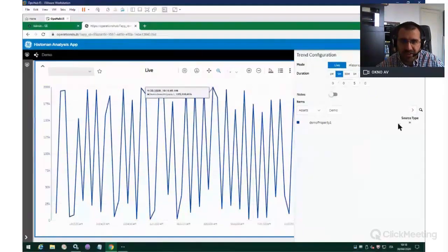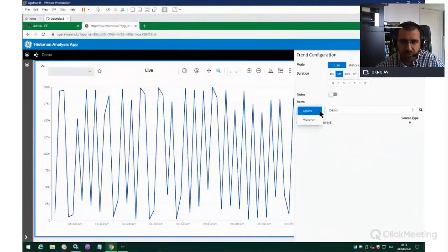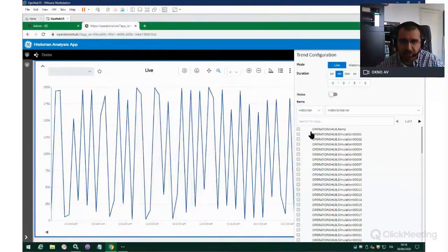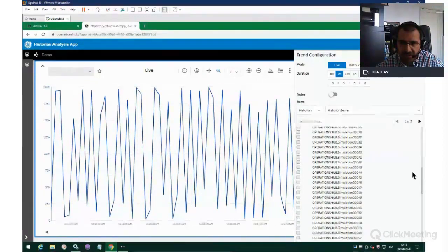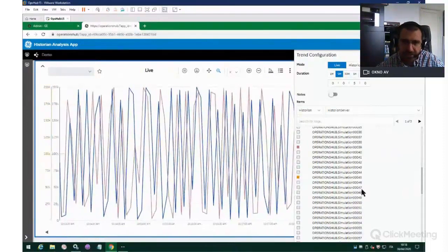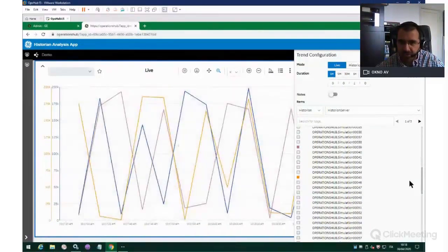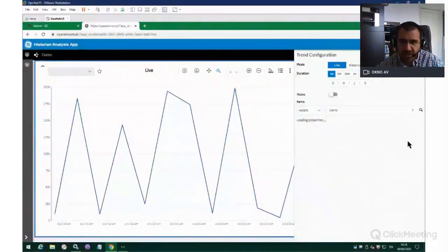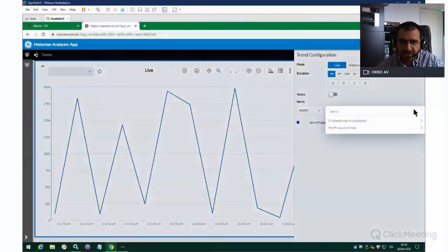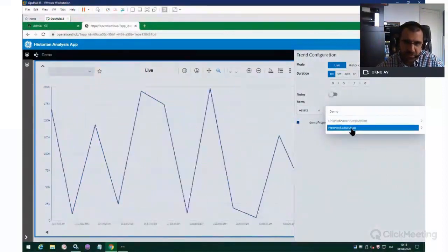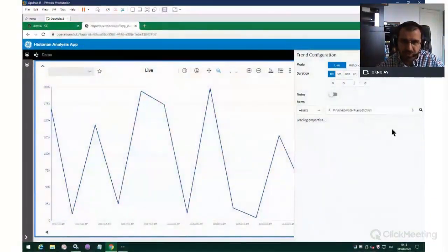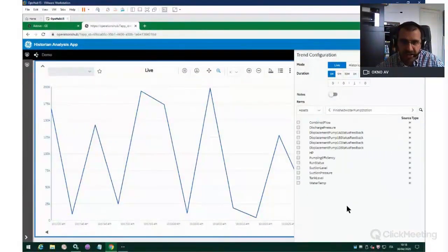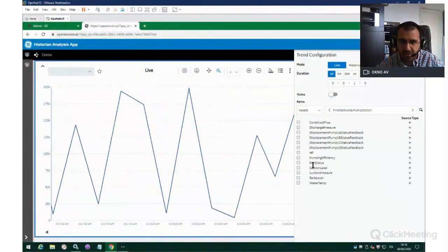And you see, this is how I select my data points. Of course, I have the classic Historian view from the server, a flat list of tags, and I can pick any tag here and just add it to the trend. Let's do 1 minute. It's a little bit easier to see. But what I really like to do is look at it from the asset standpoint. In this control, we have basically the same hierarchy that you have seen in the administration. I will go to the water pump station. And for this station, I already have some data available.